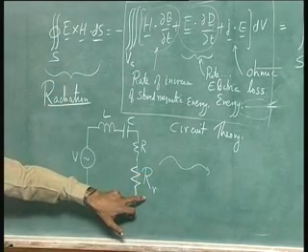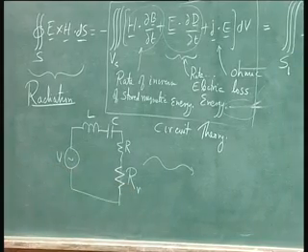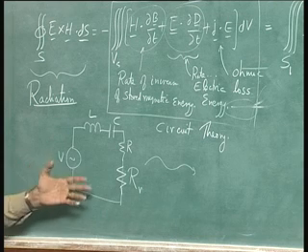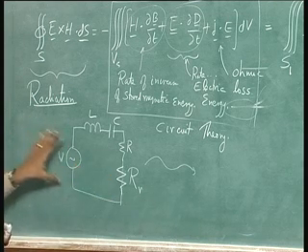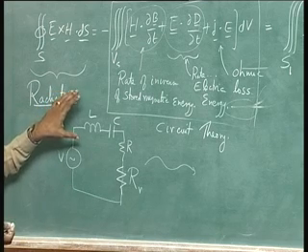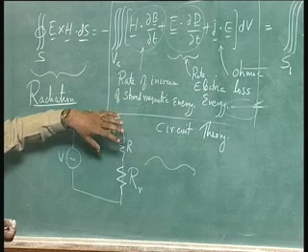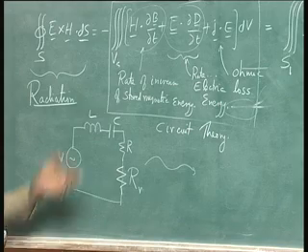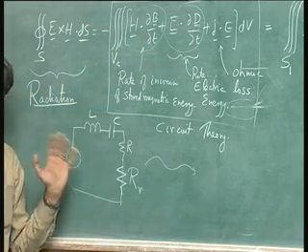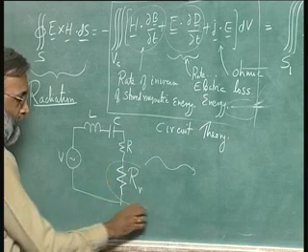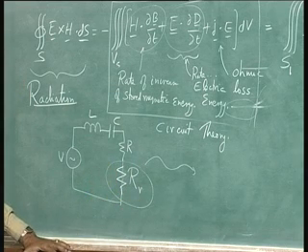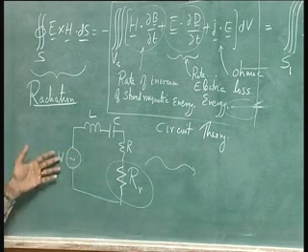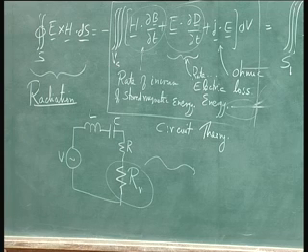called the radiation resistance. This radiation resistance is not a true resistance at all. It is an extra term which takes care of the fact that not all the energy supplied by my voltage source is getting accounted for in the inductor, the capacitor and the resistor. Some of it is just going elsewhere, and because I am able to show that it has the behavior of a resistance, I model it as a new resistor, a radiation resistance, and using it I balance my equation. In other words, I make KVL and KCL come true after all.